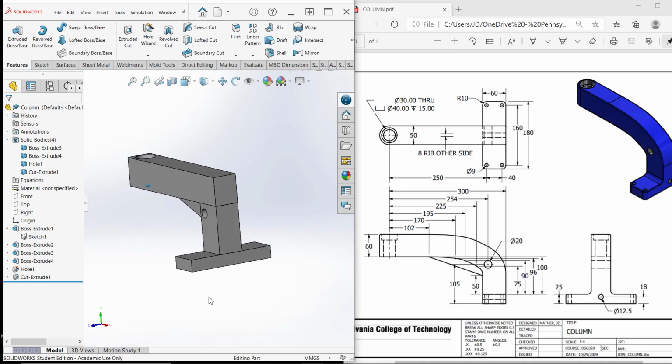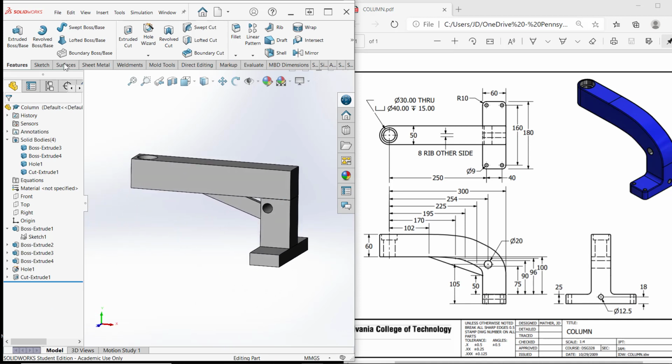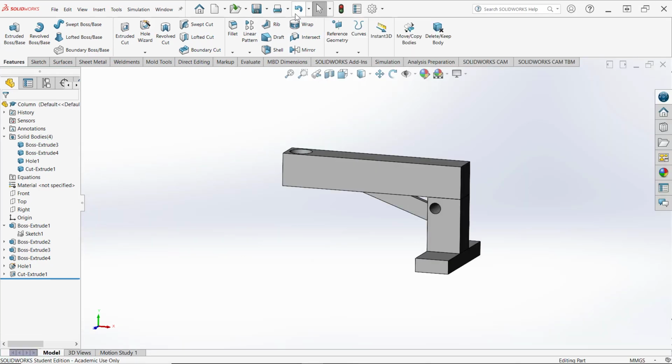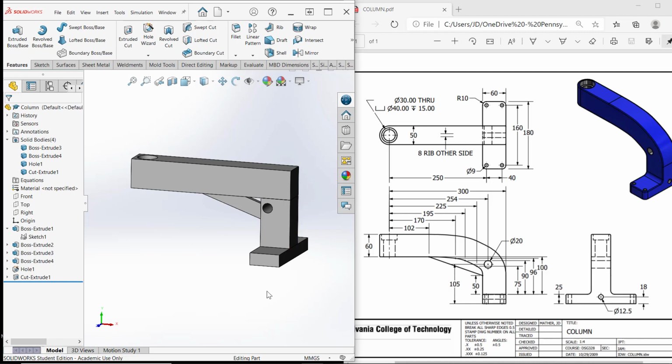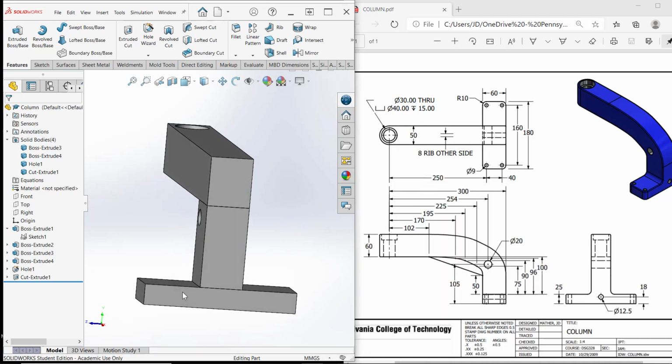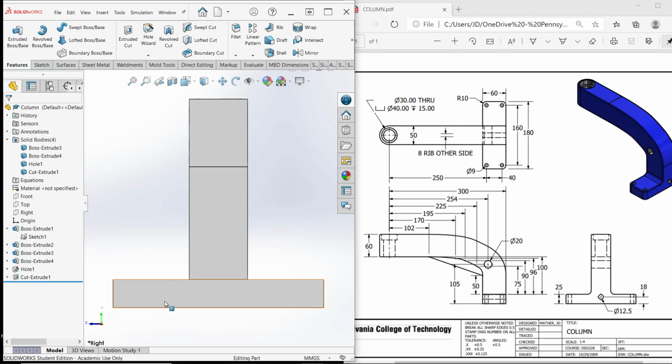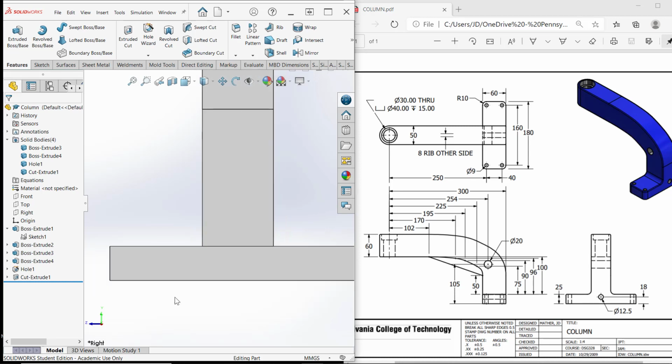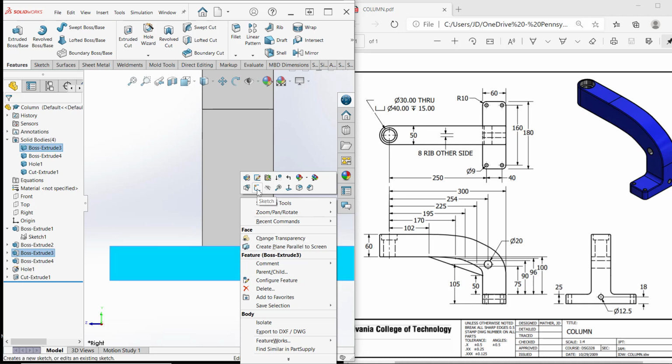Okay, so I've got that hole. Need to save this and do something right. Save it, save often. Alright, then I want to put this hole back here. So I'm going to hit the space bar. I'll go around to the right side view, and I'm going to right click on this face, and I'll tell it to do a new sketch.